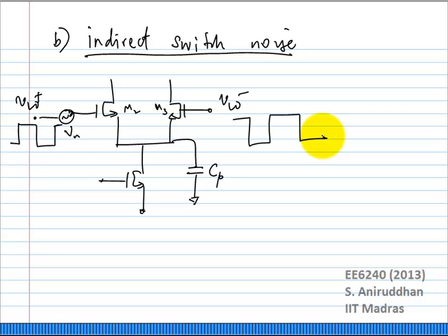Now, the way we are going to analyze this behavior is by replacing this with a single-ended cascode type stage. The only difference is, you notice that the right side switches perfectly, whereas the left side does not. Right? The right side has a perfect switching waveform, whereas the left side does not. So we are going to replace that.